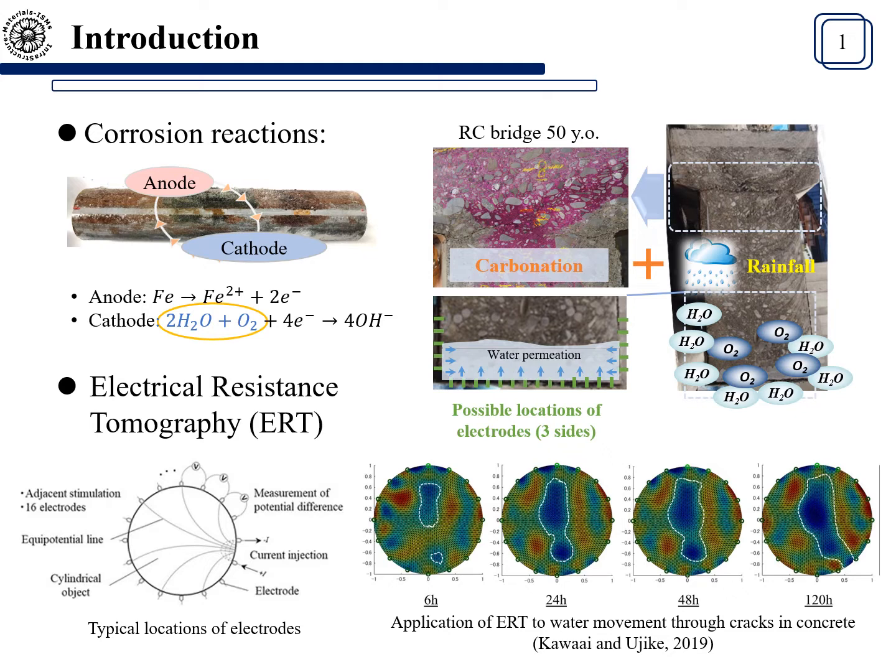When concrete structures are carbonated, the corrosion may not be severe unless water containing dissolved oxygen is supplied to the embedded steel bar. The effect of water supply may have a significant impact on the durability performances with regards to corrosion processes of steel bars when carbonated. This study is aimed at developing a new technique for assessing the ingress of water applicable to actual concrete members.